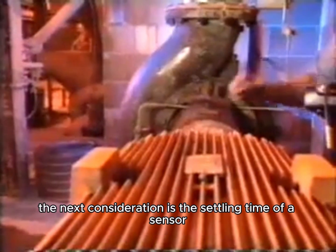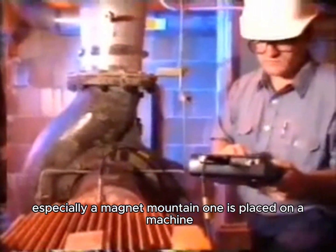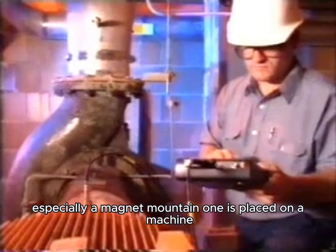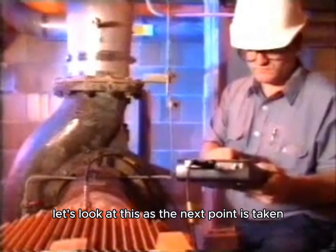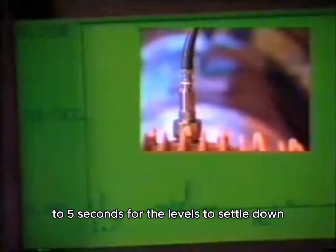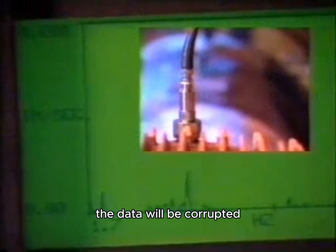The next consideration is the settling time of a sensor. When a sensor, especially a magnet-mounted one, is placed on a machine, it tends to smack the machine and shock the sensor. Let's look at this as the next point is taken. Many G's are imparted into the sensor as it is placed on the machine. This causes extreme amplitudes and will take 3 to 5 seconds for the levels to settle down. If this energy is included in the spectral averages for the measurement point, the data will be corrupted and of no value to the analyst.